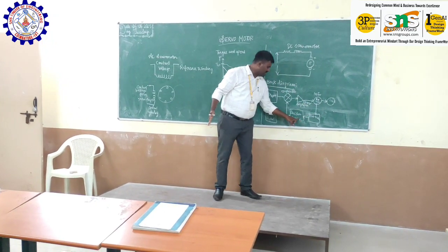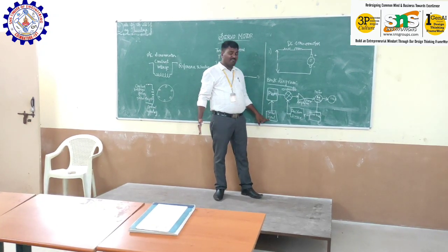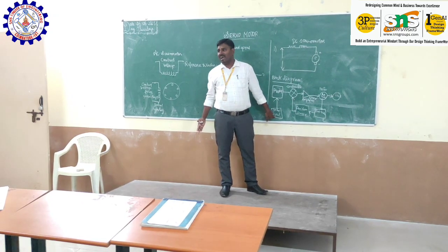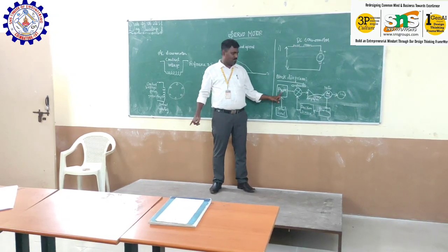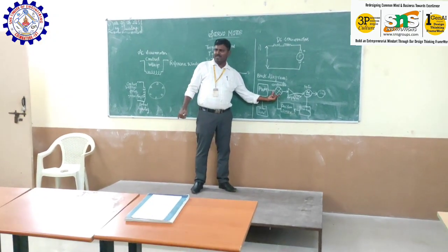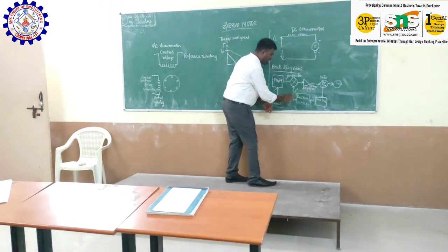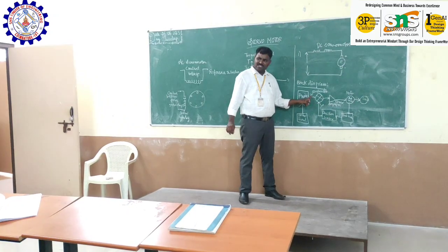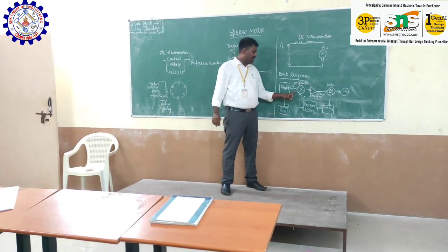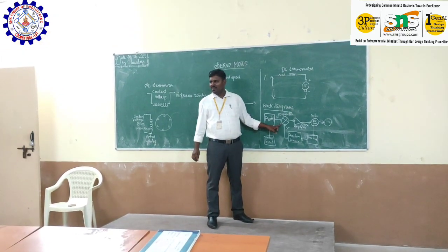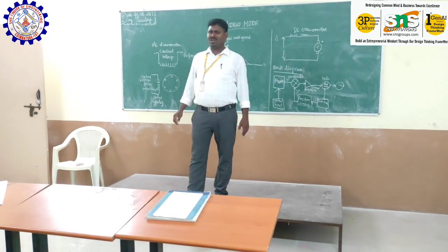Now the sensed position is given into the comparator. From the comparator, we are already giving a certain control signal, that is our expected value, called the reference signal. I am expecting an angle of 10 degrees for the rotor position, but the actual position is 7 degrees. The comparator compares the reference input with the actual input sensed from the position sensor. The difference is 3 degrees, and that 3 degrees is given into the error amplifier.